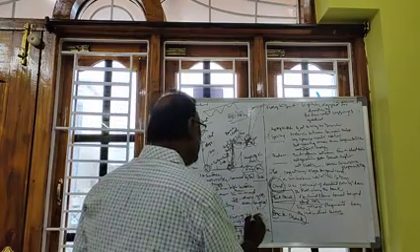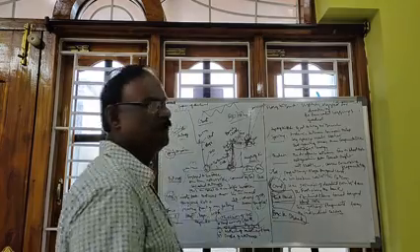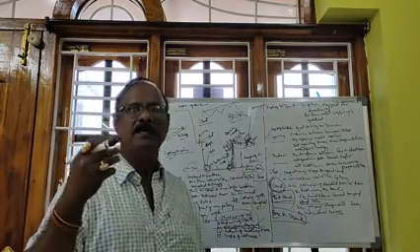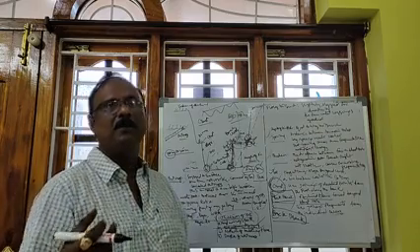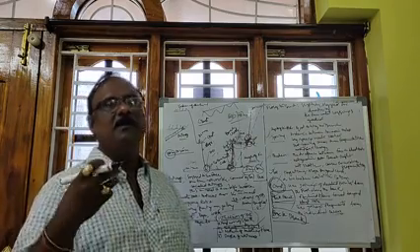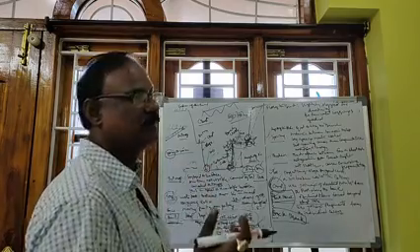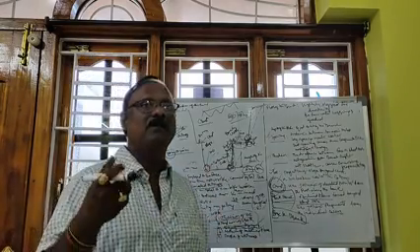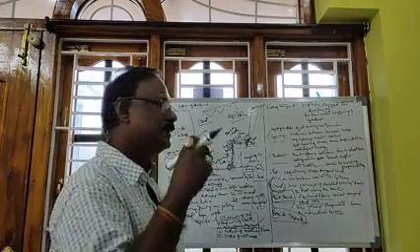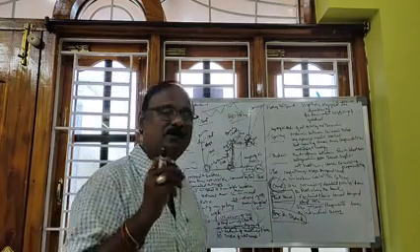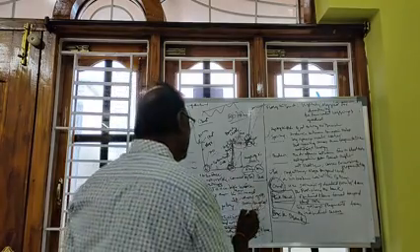And the thickness of the overburden is very high. Suppose 300 meters of overburden has to be removed. If you put 5 meters, how many vertical benches have to be laid out? 60 vertical benches, which is very difficult.